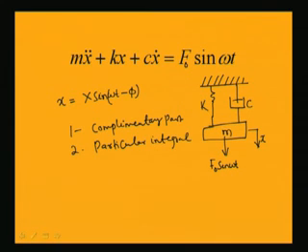We are interested in finding the particular integral of the system, as the complementary part is the same as the free vibration response, that is, the response when you take m x double dot plus c x dot plus k x equal to 0. This complementary part contains the free vibration response, and the particular integral is the solution when you take the force into account.